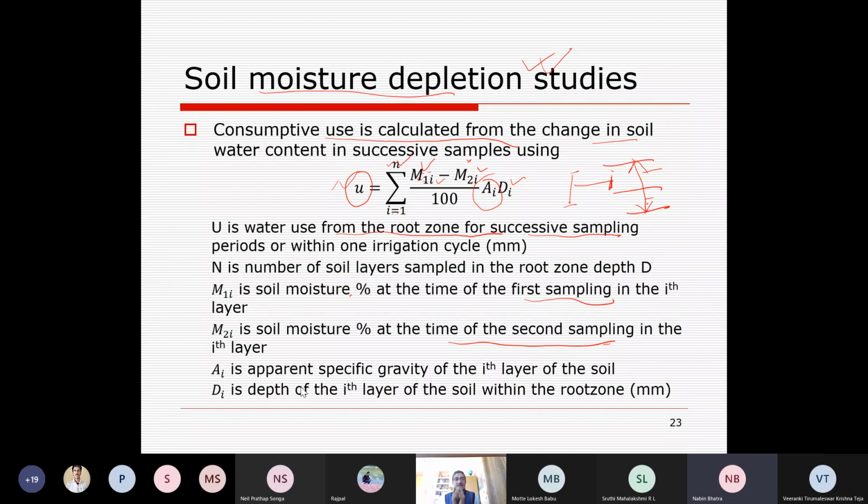So that is a simple measure that at least this resistance should be there to measure the reference evapotranspiration. And reference means what? This is basically vegetation that is taken as a reference. So this reference vegetation or reference crop should be grown in such a way that it offers a resistance of 70 seconds per meter to blowing wind. Okay, did you get the idea, sir? So that is the standard condition that has been taken there. Now next methods are, this is the measurements part, 4 methods. The basic method is lysimeter, because it's easy to get a range and to find out the amount of evapotranspiration from the area. And that is taken as the basic method to correct or to calibrate any other method.